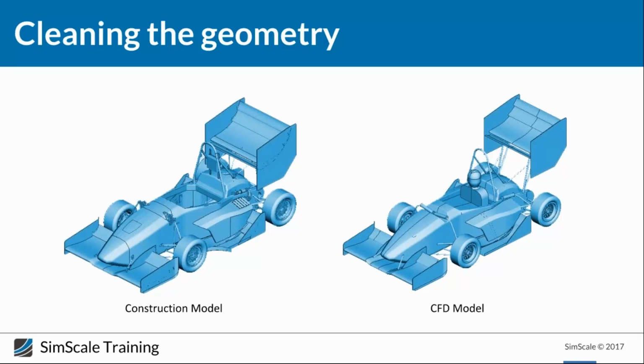Because if you defeature it, this will have a huge effect on the performance. What I suggest is to keep the vortex generator and refine the mesh close to it, to make sure you get a good representation of it and a good prediction of its physical behavior. So don't defeature the vortex generator. Defeature only the things that have more of a mechanical role in the geometry.